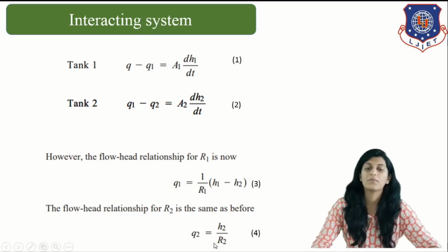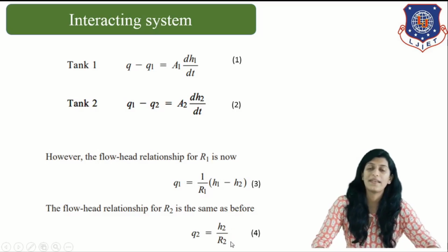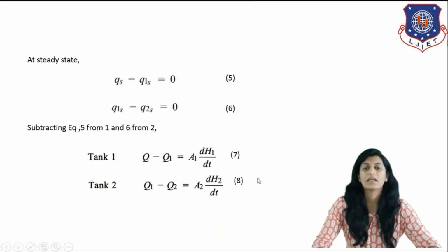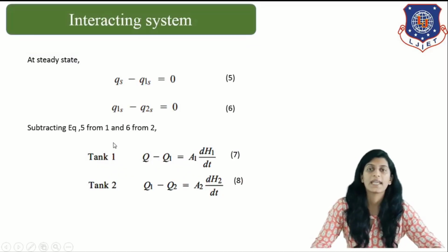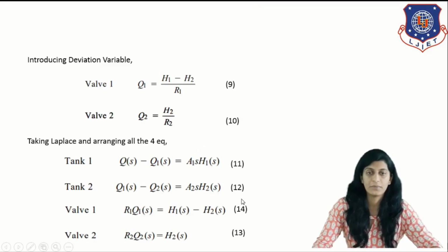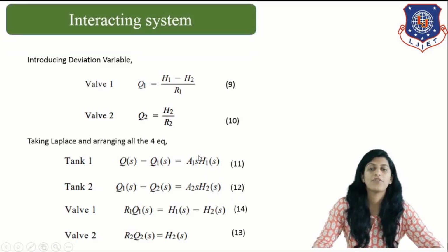In tank number 2, Q2 equals H2 by R2. After that, we transformed the terms, took the deviation variables, and then took the Laplace transform of all 4 equations.